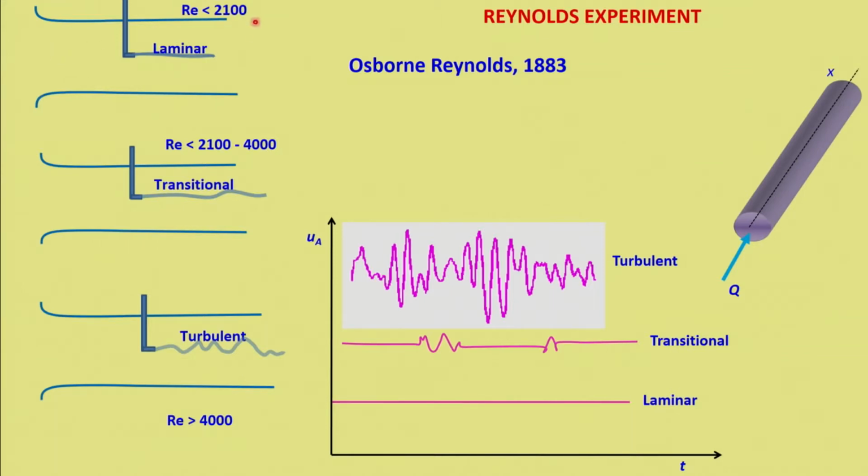That means for Reynolds number less than 2100, you put a bend upstream, a valve upstream, a 90 degree bend or 180 degree bend or 180 degree out of plane bend. No matter what bend you put or what disturbance you create upstream, for Reynolds numbers less than 2100, flow is going to be inherently laminar. That is the speciality of this critical Reynolds number 2100.